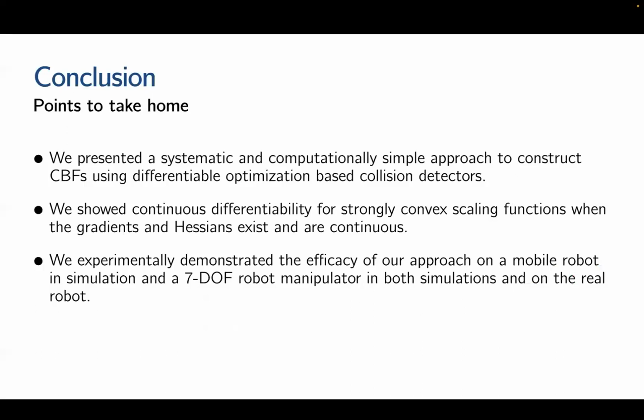In conclusion, we present a systematic and computationally simple approach to construct CBFs using differentiable optimization-based collision detectors. On the theoretical side, we showed continuous differentiability for strongly convex scaling functions when the gradients and Hessians exist and are continuous. We conjecture that the continuous differentiability can be generalized to one object being strongly convex and the second one being only convex.